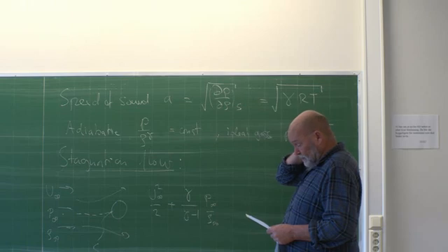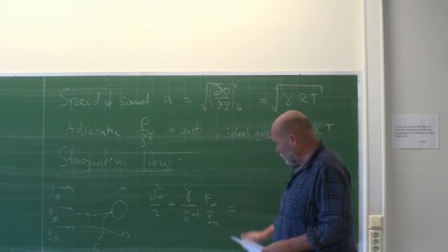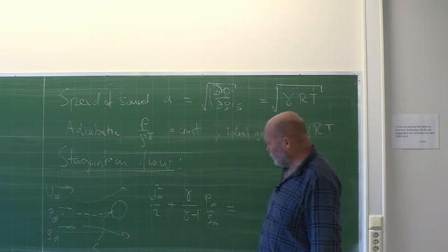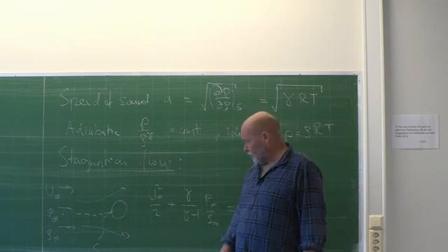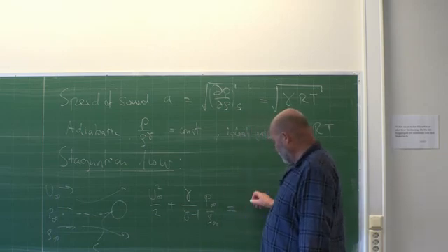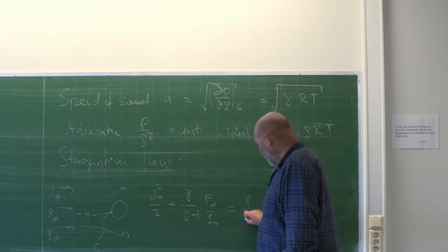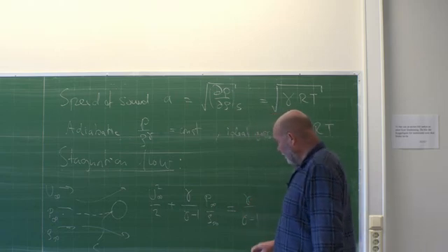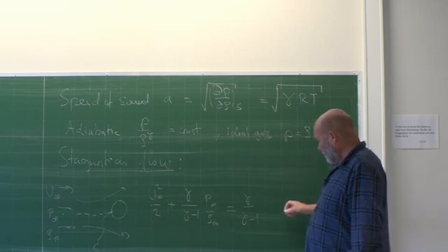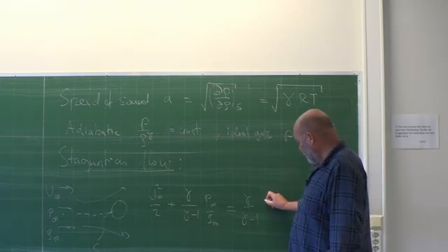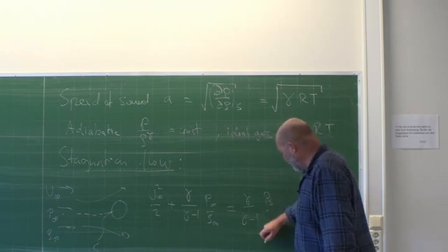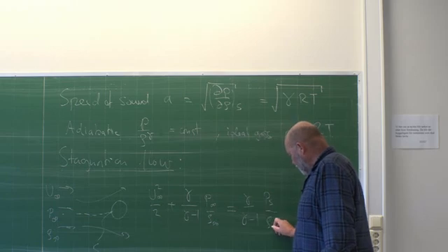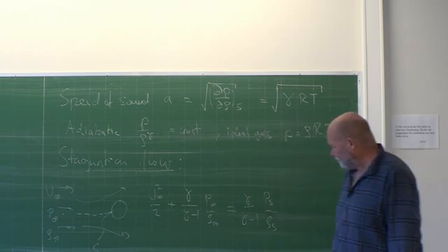And then this one equals the situation in the stagnation point. Well, then we don't have a velocity. We just have the pressure, but I still need the same sort of adjustment, adiabatic process, gamma over gamma minus 1, and then I'll have P stagnation over density stagnation, like that.